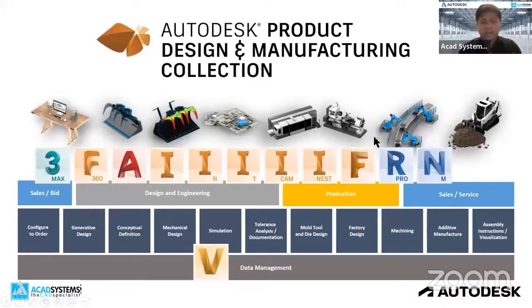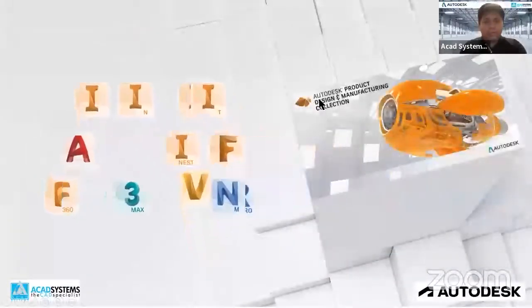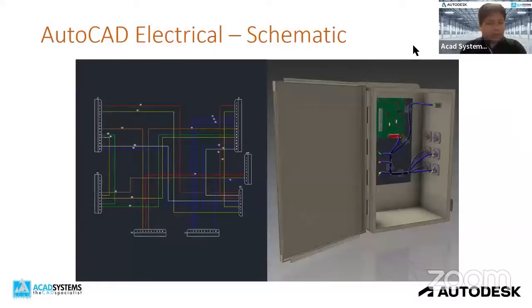But for sure, it's not in one software or one simple solution. You need to integrate between a few things. I believe you know the first one, which is AutoCAD Electrical. AutoCAD Electrical is software that is able to create schematic drawings. You can create a 2D schematic drawing, and it's very easy to create every single line and wire. In normal AutoCAD, a single line is represented as a line or a polyline. By using AutoCAD Electrical, you are able to create a line that represents your wire. You can also specify and tag the wire size and colors.